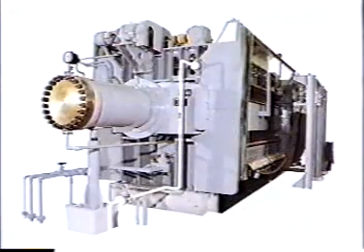With a fixed filter cloth system, the filter plates must be moved one after another for cake discharge or cloth washing. On the Model UF, however, all of the filter plates are opened simultaneously at uniform intervals, and the filter cloths move up and down for cake discharge and filter cloth washing.